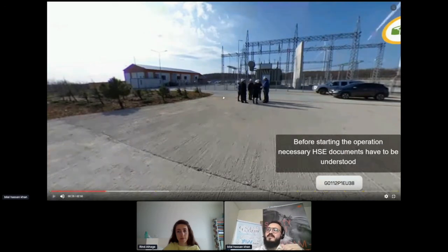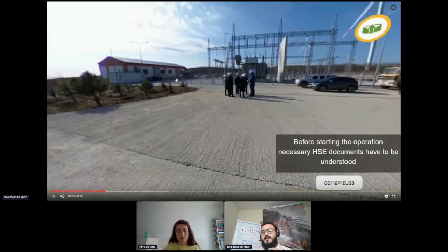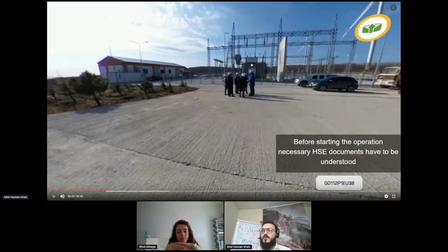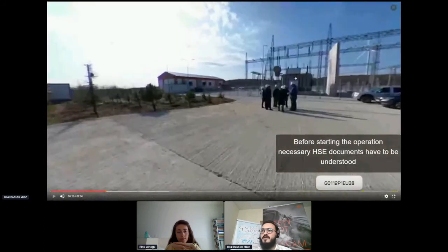All turbines are connected to the grid station, and in this grid station we have a SCADA system. A SCADA system can control all the turbines together, and we can also control each turbine individually. All turbines send their supply to the grid station, and then the grid station is connected to a transformer, and this transformer is connected to the network. It could be the power purchaser network that is purchasing the power from the customer. So this is a small view of the substation of that project.